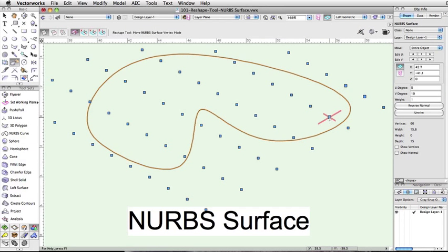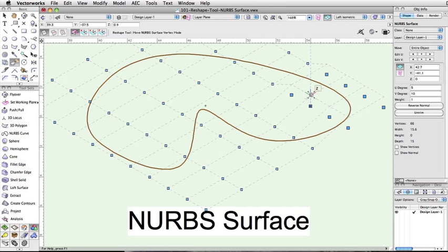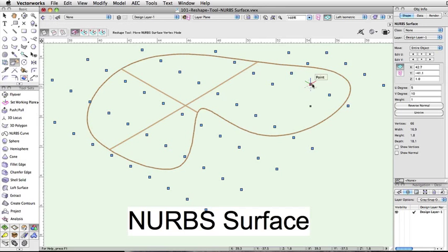A tip for working with so many selection handles: you can hold down Shift and select multiple vertices at once, allowing you to reshape a large group of them at the same time. The selected vertices are indicated by an increased size in the selection handle.